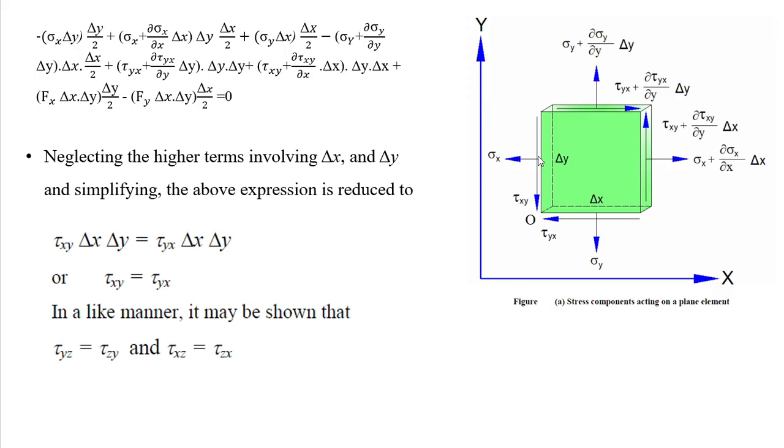You can get the force from this particular element in this direction. This normal stress now acts as a force. If you see in this diagram, when you take moment about this point, this force is acting in the negative direction. Anti-clockwise I am taking as negative. So σx into δy is the force, and it is acting at a depth of δy/2.